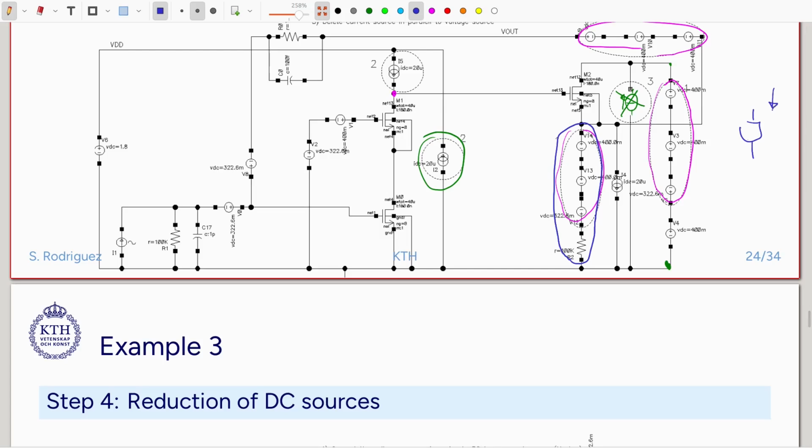So if there is some current flowing here, we can use a resistor to make the voltage drop, and for AC we can put a capacitor in parallel that shorts these two nodes, so it is a decoupling capacitor, so it shorts these nodes for AC, but probably that will be okay at board level, but in an integrated circuit we might try to avoid this implementation.